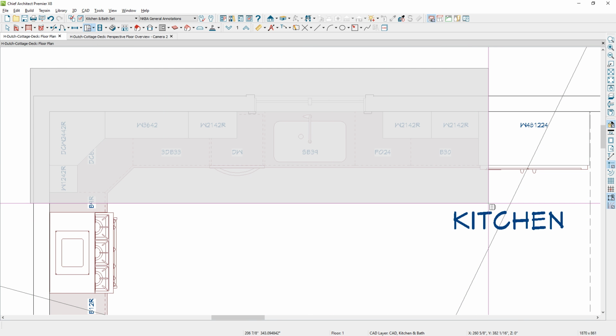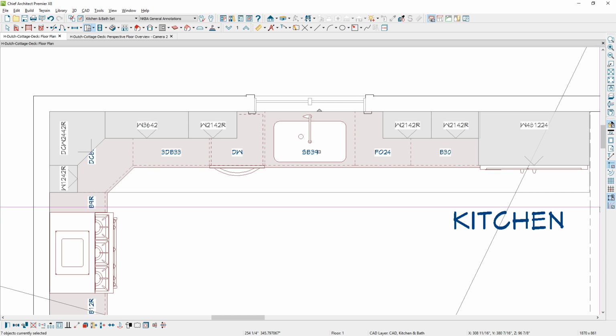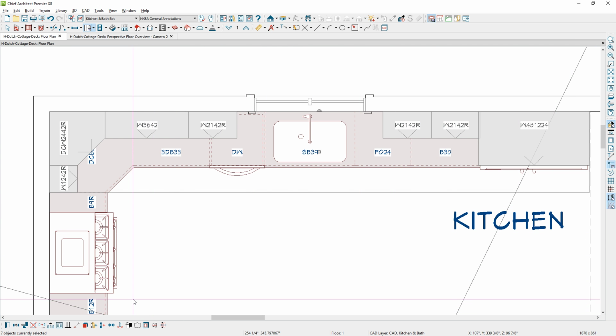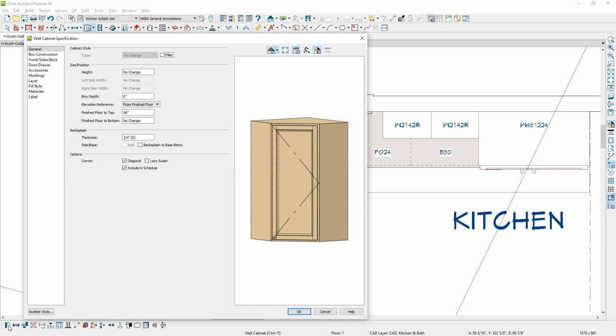Now I'm not drawing around the top of the wall cabinet over the refrigerator yet, but let's go ahead and grab all of them, and now I've got them all selected. Notice in the very left-hand corner of your menu it says 7 items selected. That's how you know what is selected, and now I can simply press the open button down in the lower left-hand corner and open up that cabinet dialog and make changes from here just as we did earlier.